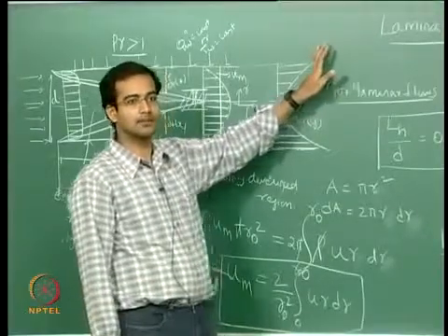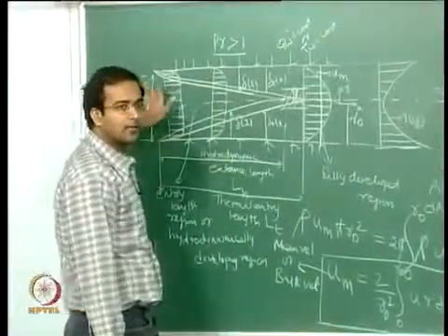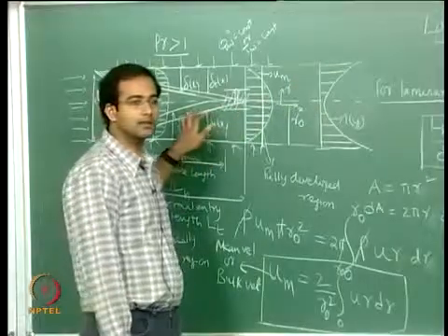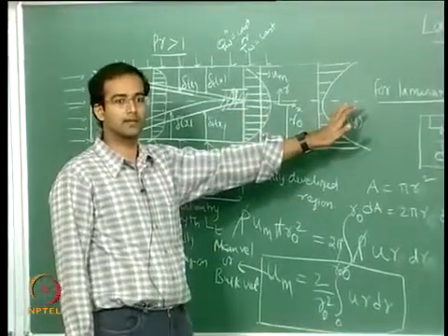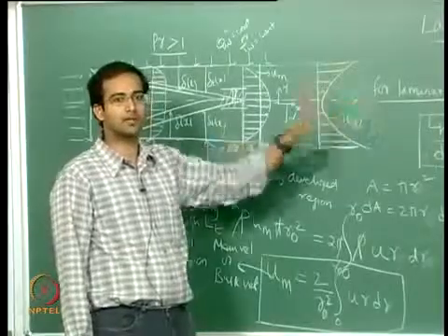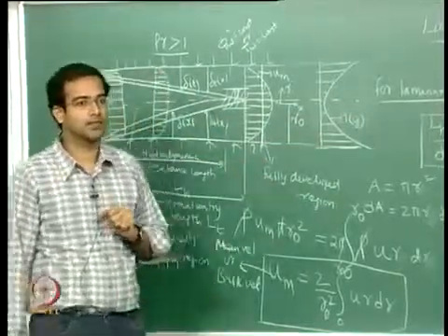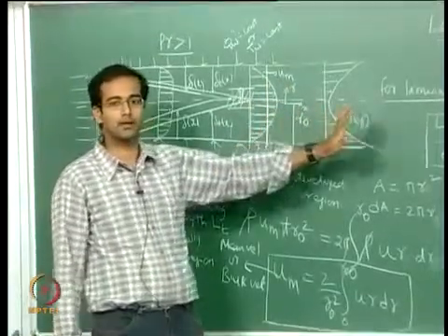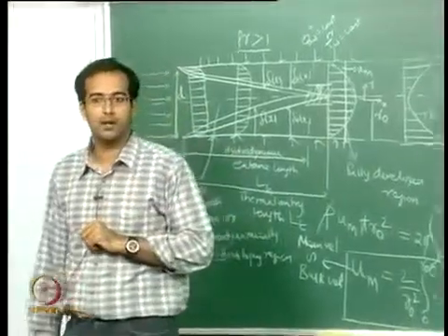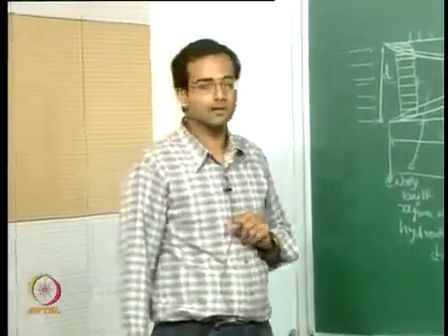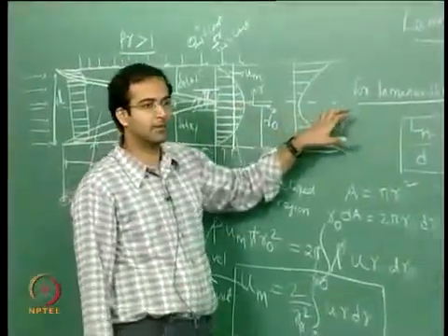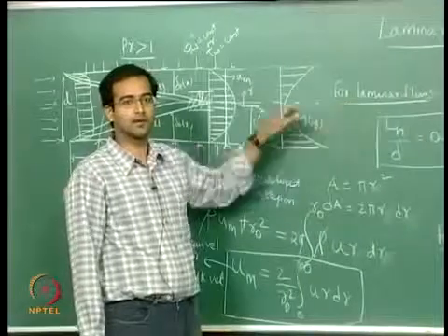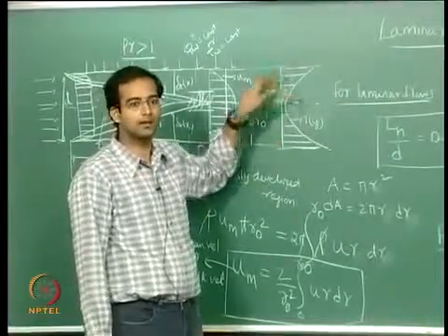adding heat. So therefore, due to conduction, the wall temperature has to keep increasing downstream, and consequently the fluid also keeps getting heat continuously. So the fluid temperature also has to vary along the x. So therefore, unlike the velocity profile which shows a constant behavior, the temperature will never be a constant value, correct? So you will find the temperature of the fluid anywhere that you plot will keep on changing with respect to x at any y location, or even at the wall that also keeps changing.